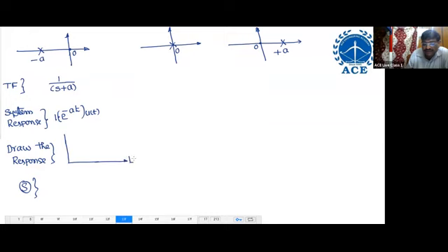Now draw the response. At T0, it starts at 1. At T infinity, exponential decay. System what? Stable. Bounded response, stable. Or the output follows the input here. This is the output. Input is 0 here. Impulse means what? Impulse exists only at t equal to 0.